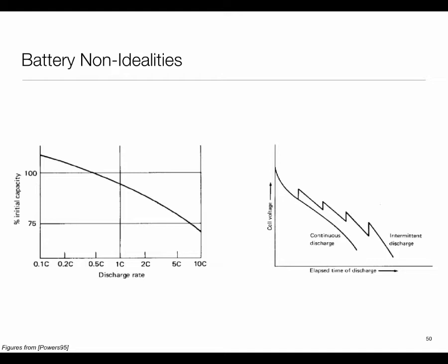And when you combine it with things like changing voltage and frequency, they can become a very important thing. So for example, if you look at, let's say this is a battery, and what this is showing is how much capacity of the battery I can get depending upon what the current is. This is in some funky units, so ignore that. But all it is saying is if I am operating at a high current, I get less energy and therefore less lifetime out of the battery. And if I'm discharging it at a low rate, I can get more energy out of the battery. So the remaining energy kind of gets wasted.